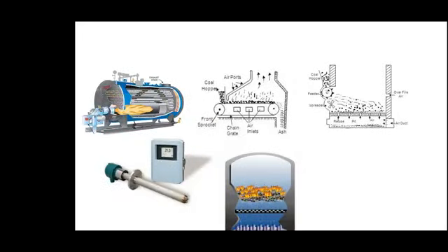And these are the various boilers that are in use. So basically a boiler converts the heat in the fuel to heat in water or heat in steam. Traditionally, we have these liquid fuel or gaseous fuel boilers, where the flame goes in through the tubes and comes out through the chimney. For solid fuel, we had different types. These are the stoker fired. Coal is dropped here, it moves through a grate, and then it burns, and the heating coils are here, so steam is produced.